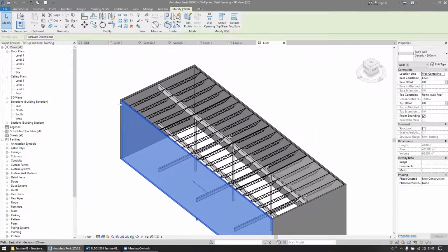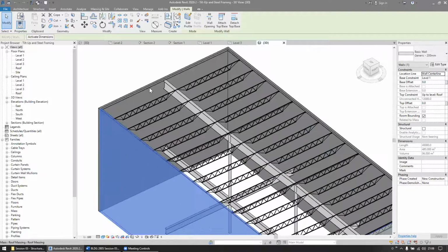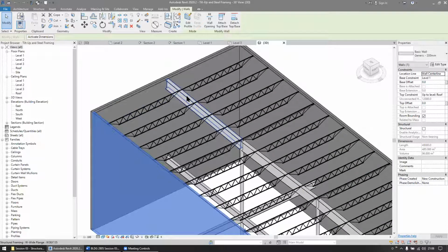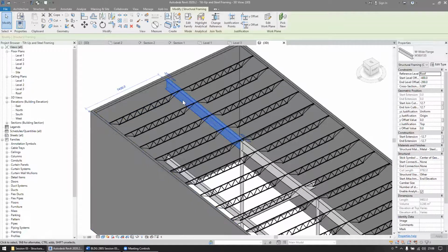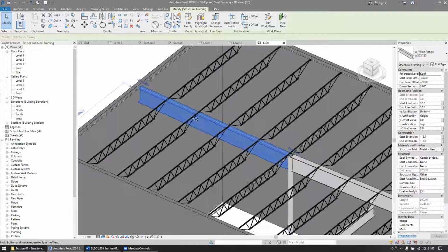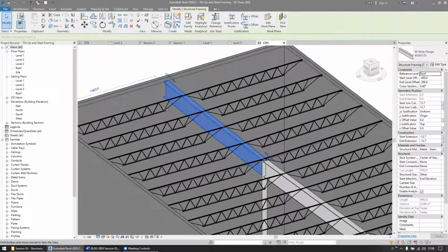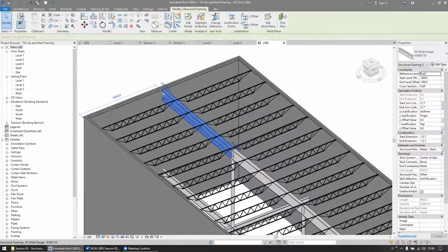And quite often the structure inside for the floors and the roof is steel. So this is a non-combustible building. And often to make drainage work on the roof, they will employ sloped structures. So here we've got a beam that's in turn supporting our open web steel joists for the roof. It slopes from the roof edge down to a column that's at a lower elevation.